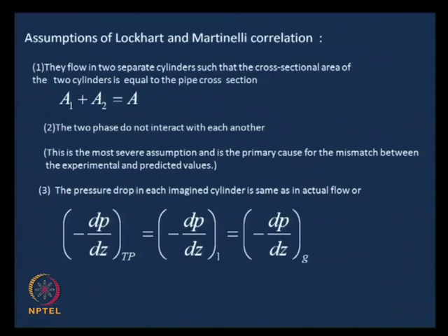This was a very serious assumption, and that we will see shortly. In fact, I had started in the last class. I had tried to apply the separated flow model after deriving the analytical expression. What I tried to do is find out phi L square for annular flow by considering the actual flow circumstances and by considering the Lockhart-Martinelli correlation, and I wanted to show you how well these two expressions agree. I could not complete it today, I will be completing it.